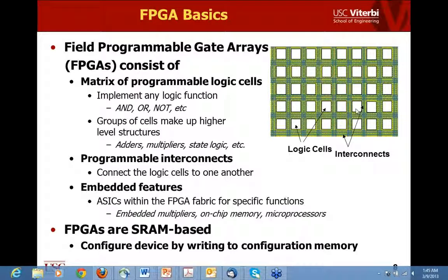logic cells, what I see here in these small boxes, and some connecting patterns between them. So I can synthesize a particular application's required functionality by configuring those logic blocks, by actually writing into the memory locations of those logic blocks, and then also figuring out and implementing those connections between those logic blocks. So I can build, for example, an adder at this point in the upper right-hand corner here by using various cells depending on the number of bits I have in the adder units to be added. So I can build those particular adders or a multiplier by configuring those individual logic cells and making the connections between them.